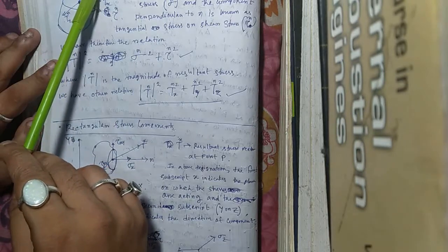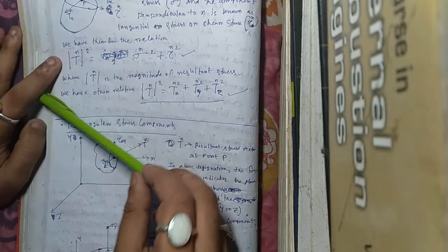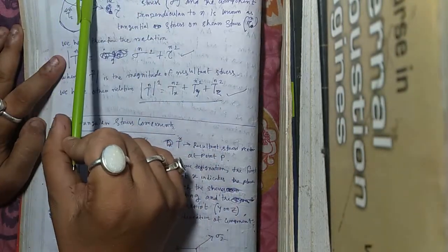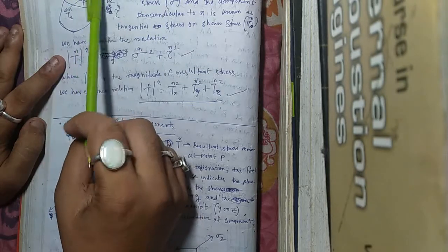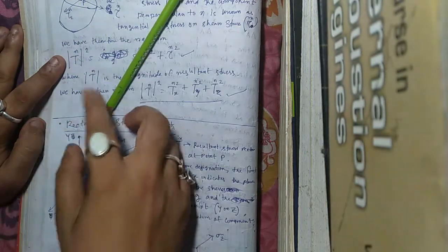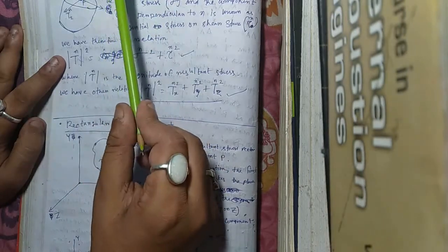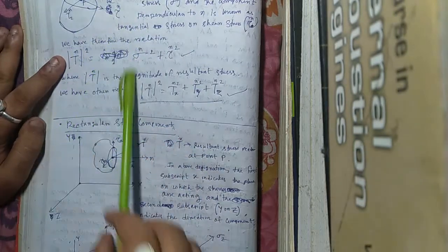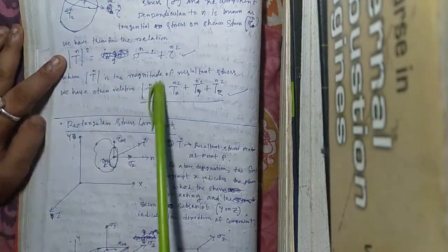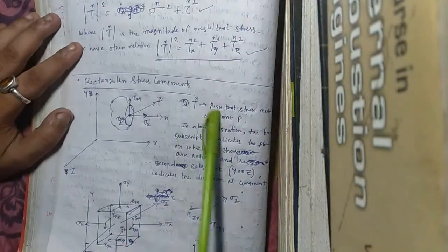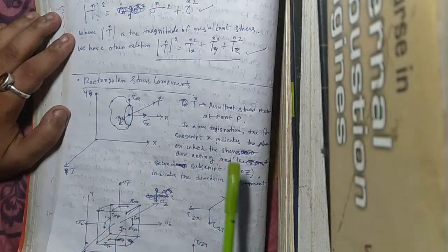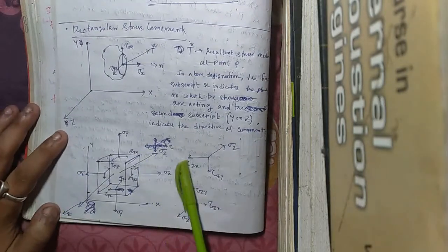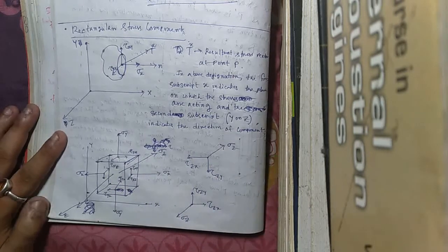The stress along the direction of n is known as the normal stress sigma n, and the stress in the perpendicular direction is known as the shear stress, denoted by tau n. And these are the rectangular stress components drawn on three mutually perpendicular planes by drawing a cube.